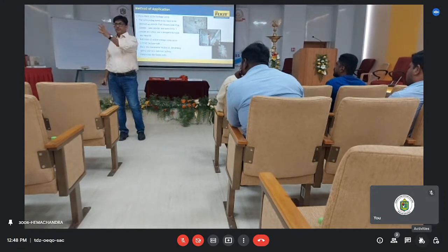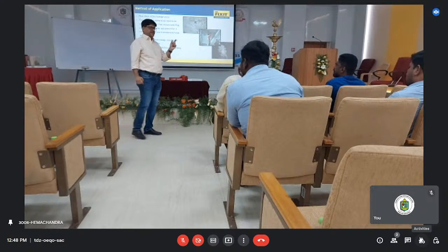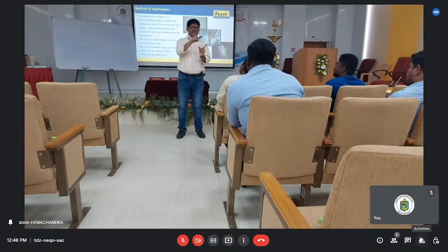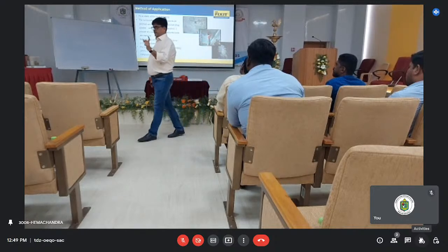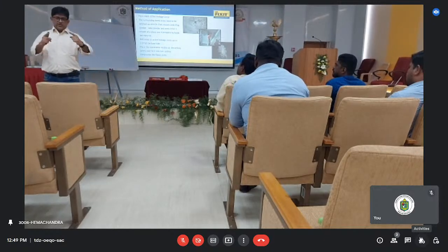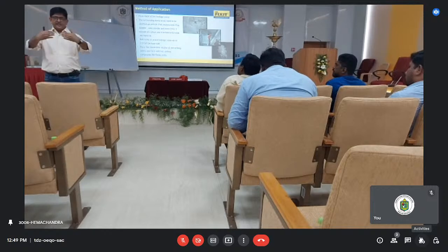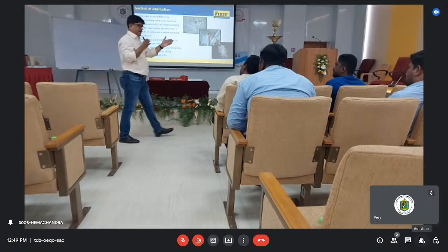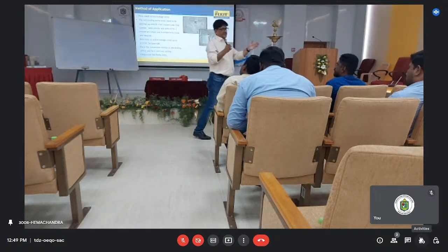All people who know grouting know there is a principle: whenever you are putting the grouting material, you have to maintain a center to center spacing between the drilling holes. The C2C spacing is very important because if you do not have a proper center to center spacing, the material will hit a hindrance and give you a back pressure. So depending on the situation, you have to have a minimum center to center spacing.